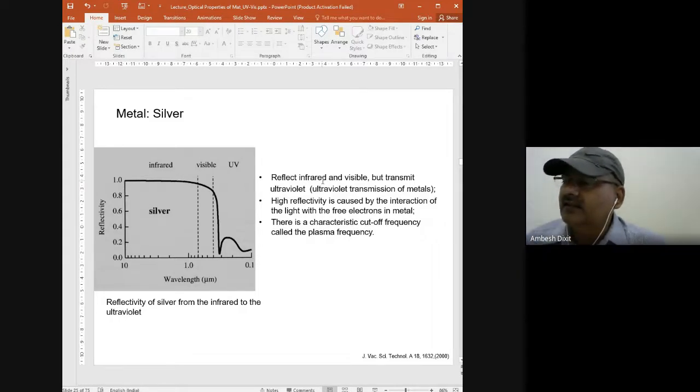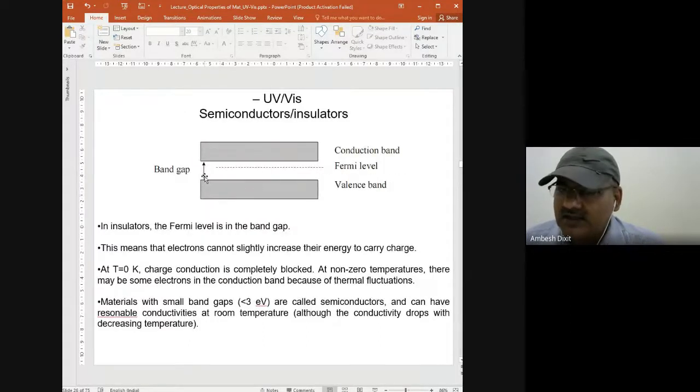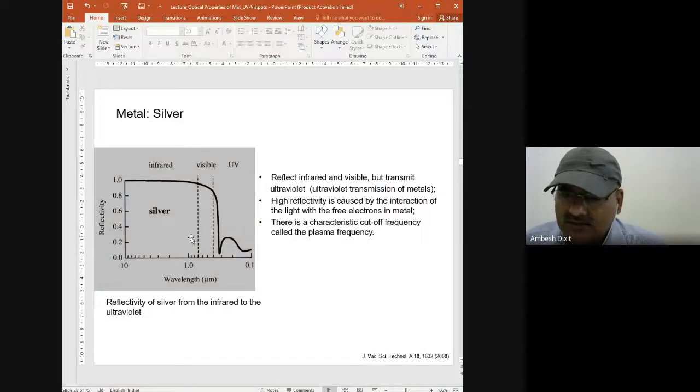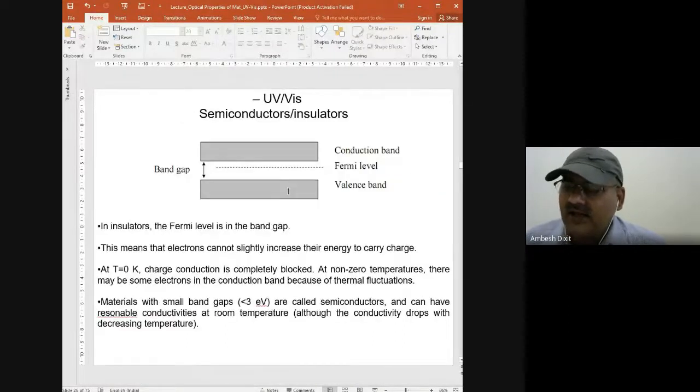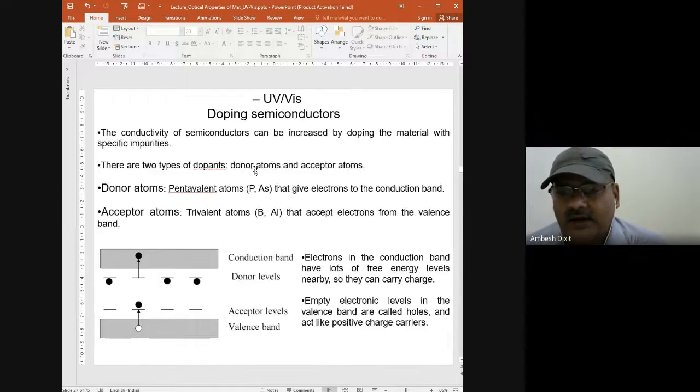That's why silicon is transparent to infrared light. It can pass through your material, which looks opaque to your eyes when you visualize it, right? But as soon as the light comes near approximately 1 electron volt, you will see that the interaction starts, and photon energies are absorbed, taken by electrons to move them from the valence band to the conduction band. And this phenomenon we can use again to find out the nature of the band gap as well as the numeric values of these band gaps.